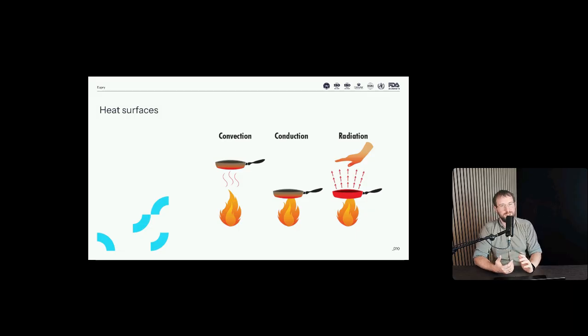Another part is conduction. We don't often see conduction in mappings, but basically if you touch something and it transfers heat, that's conduction. And then we have a really hidden risk here, which is radiation. Whenever we have a radiator and it's heating up, it will radiate invisible light, to the human eye, towards the surrounding air. That means not only does the air increase in temperature, but products that are placed close to the radiator will also experience this radiation heat.